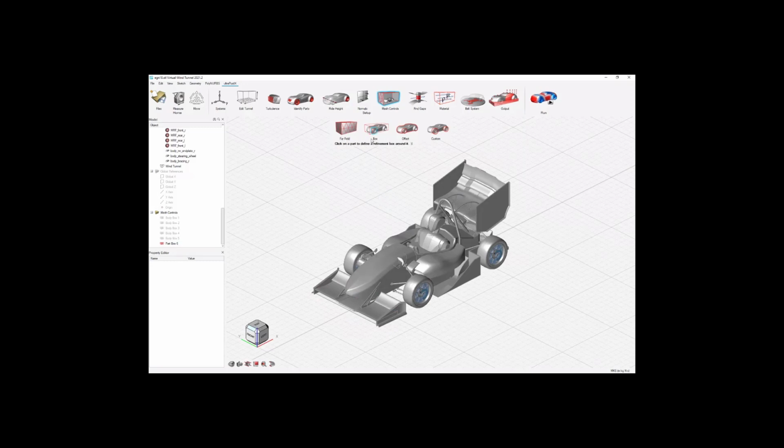And now also for the rear wing, you can select many parts by holding down Control. Now both of those end plates will be included, but again this doesn't really matter because we will set up the dimensions manually. Again, for that I will define refinement level 6, because in the front wing, the under tray and the rear wing you will have the biggest pressure gradients, so you also want to have the highest resolution to make sure that the flow is simulated properly.